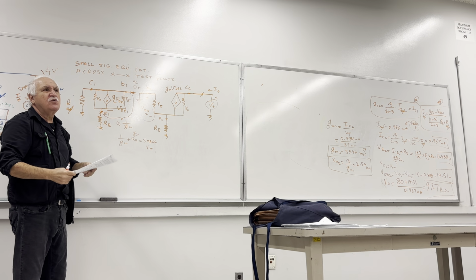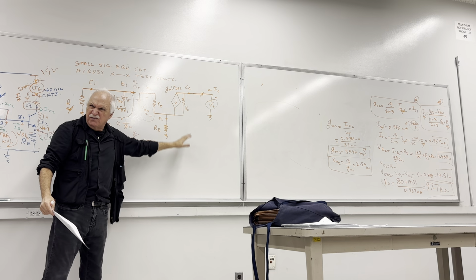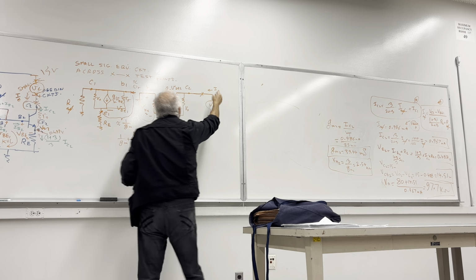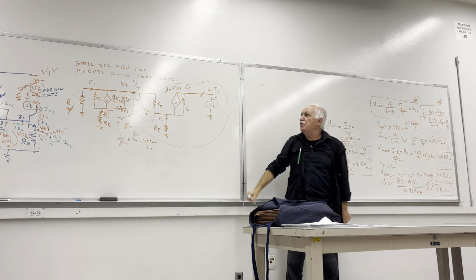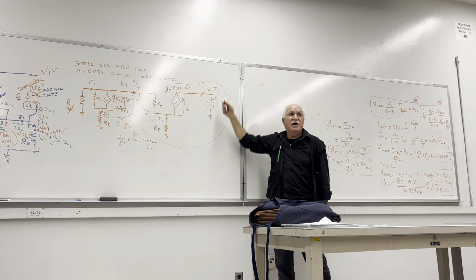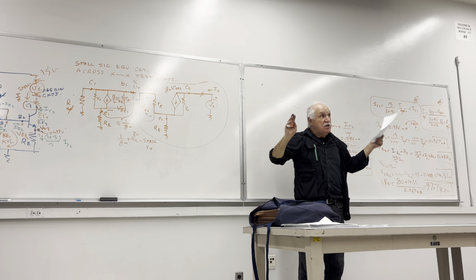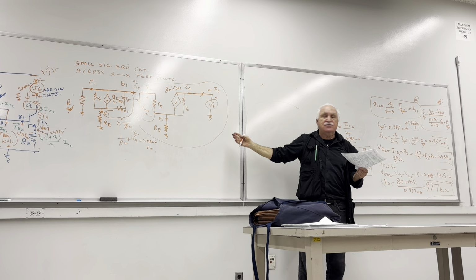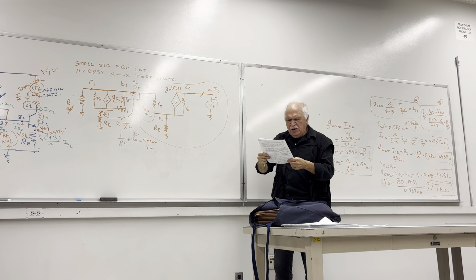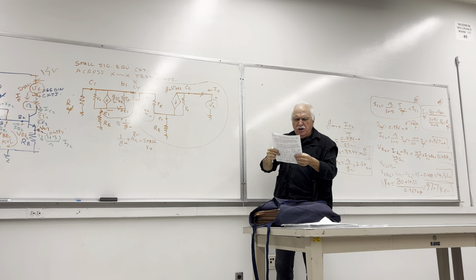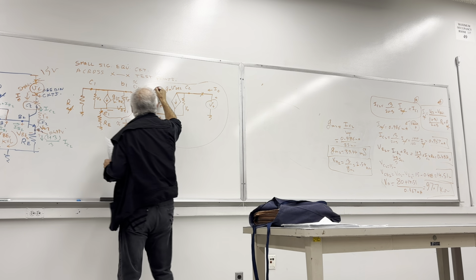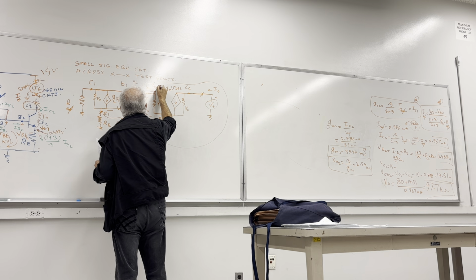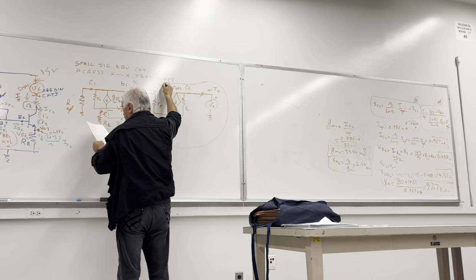Then, what will be your equivalent circuit? Kind of a little modified equivalent circuit. It's this kind. So we need to prove VT over IT ratio has improved considerably. We need to prove that. Okay, so how do we prove that? Assume that IB2, the current that might exist here, is much, much smaller than the IT.